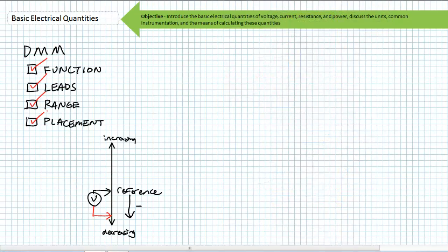Realize if the battery was being measured while it was charging, we might see a higher voltage, something like 13.8 to 14.1 volts. And if the battery was discharged, we might see something like 10.6 to 11 volts. Additionally, if we measured this battery while you were trying to start the car, or drawing a substantial amount of current from it, we would see a voltage fluctuation downwards from 12 volts. This is just a glimpse of the many tentacled monster I'm desperately trying to keep a lid on. Batteries aren't perfect ideal sources, and we'll get into their non-ideal natures in later lectures.